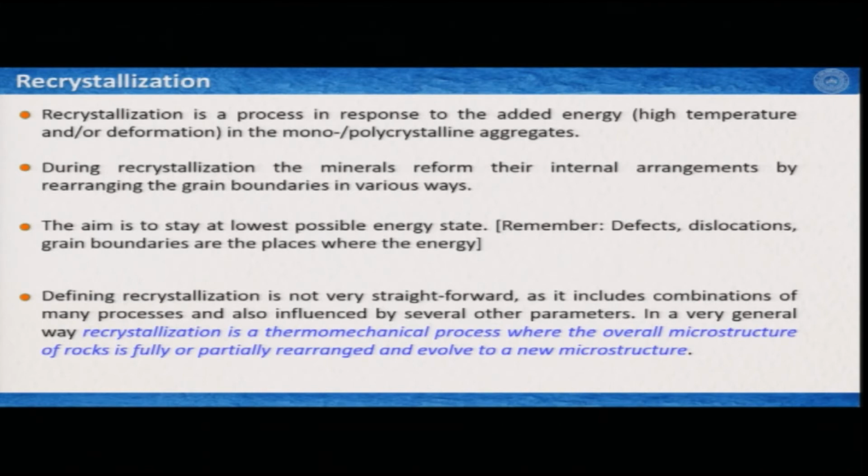So, during recrystallization, the minerals reform their internal arrangements by rearranging the grain boundaries in various ways. We will see those very soon. And why do the crystals rearrange their grain boundaries? The essential aim is to stay at the lowest possible energy state. So, if you remember, the defects, dislocations, grain boundaries, etc., are the places where the energy stays, right.